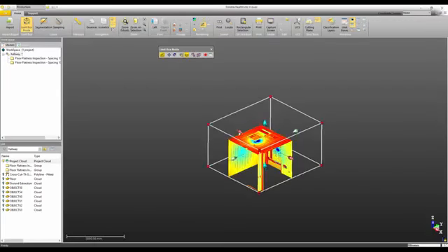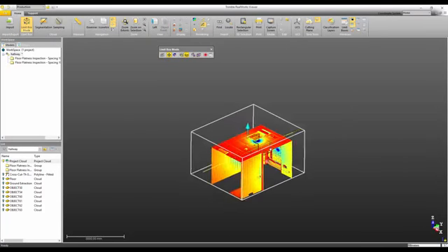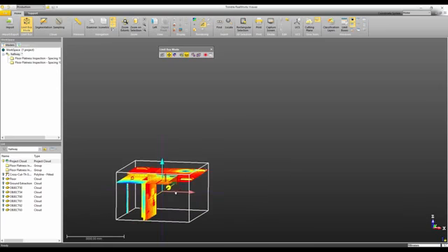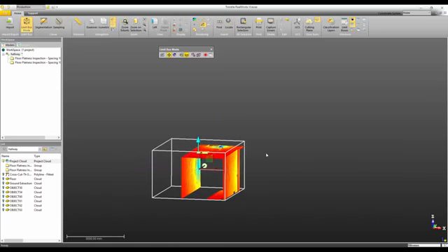In addition to changing the shape of the box, you can also pan to move the box. This is done by clicking on one of the grab handles. It can be any of the corner or specific face handles. Just click on it and you'll see it'll toggle through now to allow you to pan the box along any of the axes. Panning the limit box is a great way to inspect areas such as corridors.